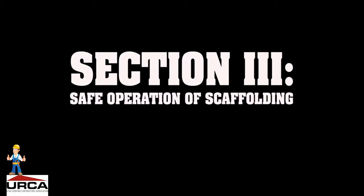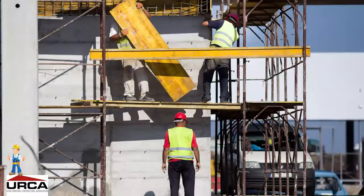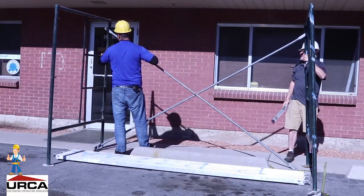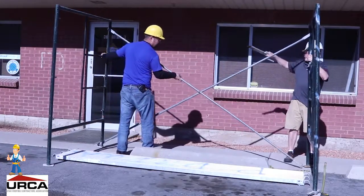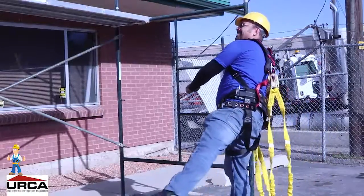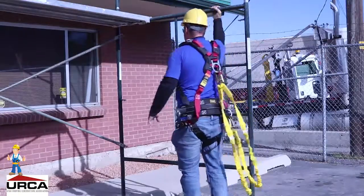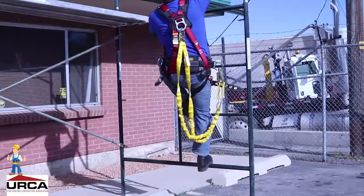Scaffold safe operation. Chances of injury are greatest when erecting and dismantling scaffolds because they are incomplete and not secure. Employees involved with setting up the scaffold or near it must wear hard hats. A competent person determines whether erectors should wear a PFAS while erecting or dismantling scaffolding.